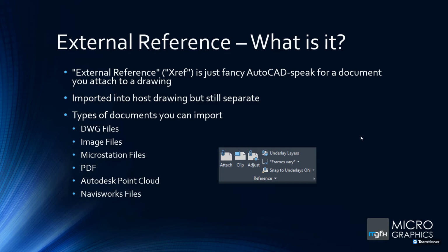And the final one over there is the Navisworks file. Navisworks is another program from Autodesk which allows you to bring in files from a whole different range of software packages, not just Autodesk packages. It really makes it a light file, so when you navigate through it, you are able to do it quite quickly. If you started importing large files into AutoCAD from other people, it really does make the AutoCAD file really, really big. So Navisworks allows you to do that and make it lightweight as well.